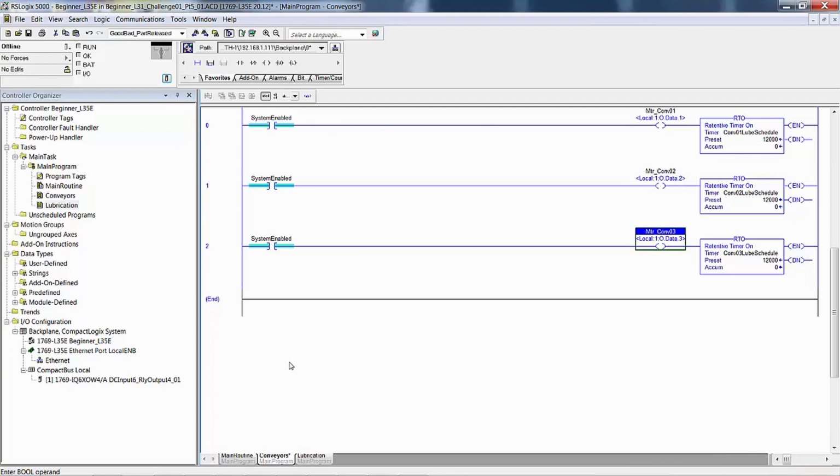When conveyor 3 calls for a part, and if both conveyors 1 and 2 are full, and there is another part ready at the entrance of conveyor 1, all 3 will run until the new part is fully onto conveyor 1. At that point, conveyor 1 and 2 will stop, but conveyor 3 will continue to run until that part was pulled onto conveyor 3 and has exited conveyor 3 completely. That would be called a takeaway conveyor.